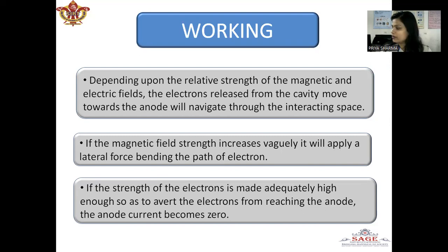The magnetic field required to return electrons back to the cathode, just grazing the surface of the anode, is called the critical magnetic field, also known as Hull's cutoff magnetic field, whose equation is used directly in exams and numericals.